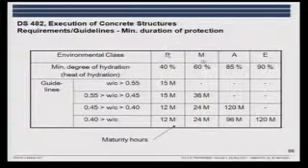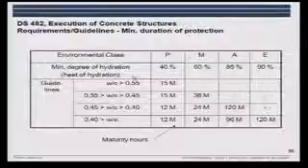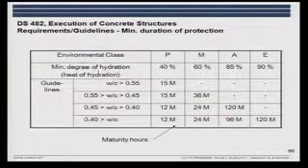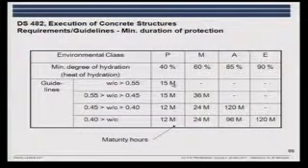We have different environmental classes: the passive, moderate, aggressive, and extra aggressive. So passive would be in here, where we don't have any problems with the deterioration mechanisms. Extra aggressive would be the edge beams, for instance, or splash zone in marine structures. Preferably you should determine the degree of hydration, but that's not practical. And then instead, there are requirements to the age, the maturity age.